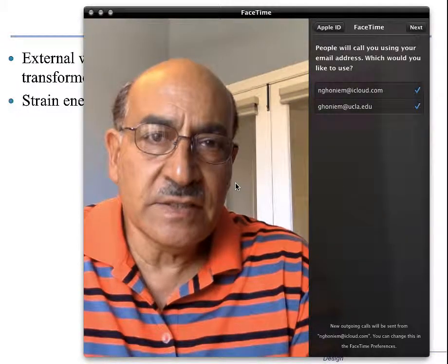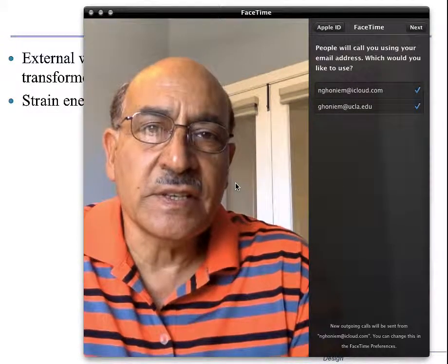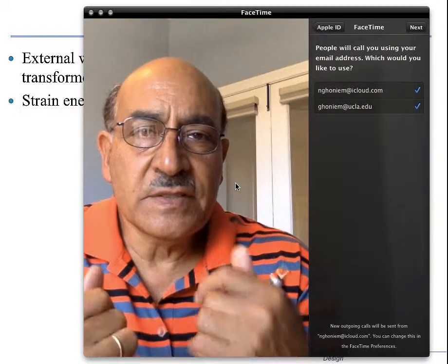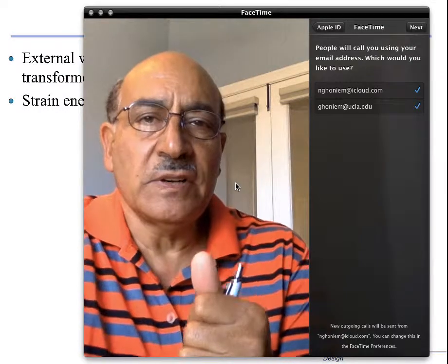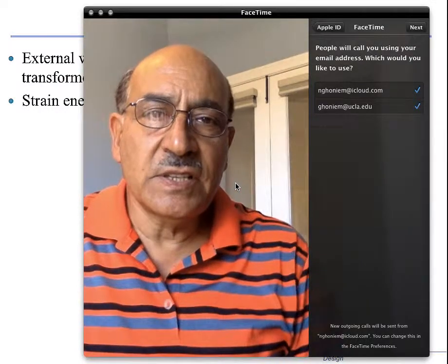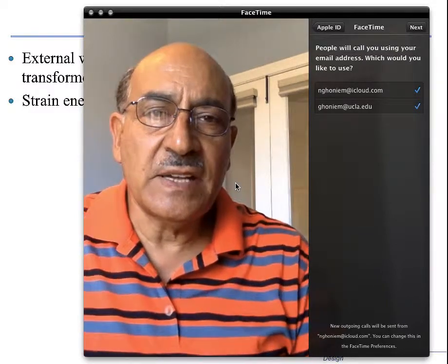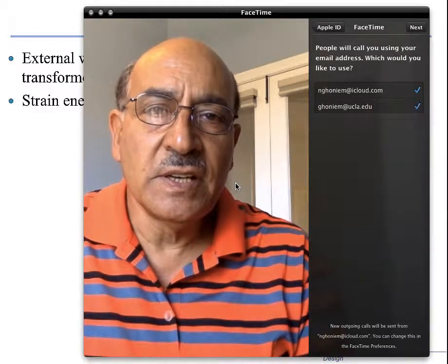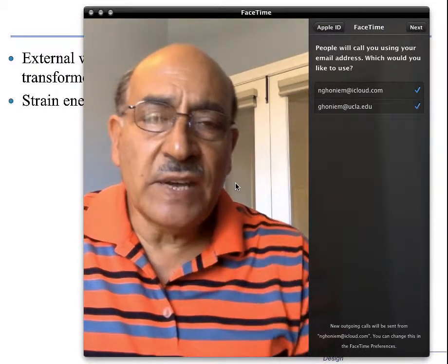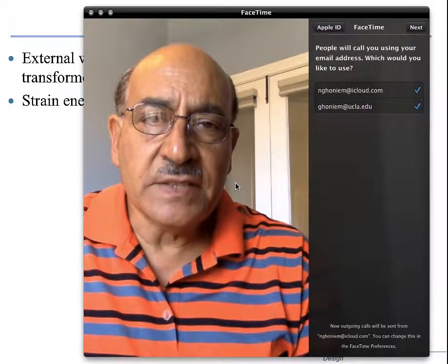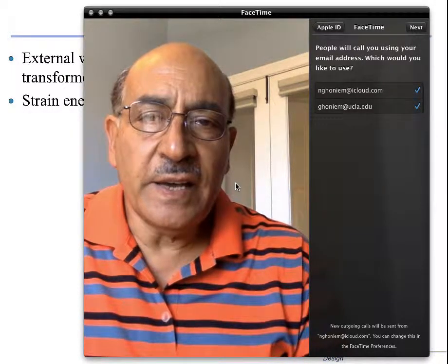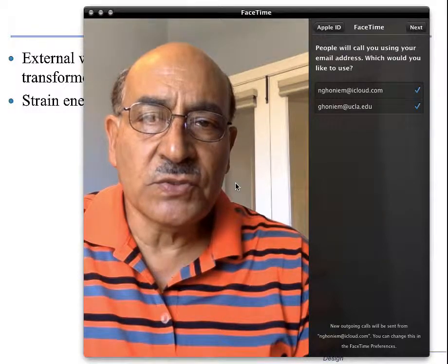So in fact, there's two elements of this presentation or this section. One element is number one, how to find the elastic energy stored in a section of a beam or a tension member or a torsion bar. And then number two, once you find that out, how do you utilize the expressions or the formulas that you'll get in determining deflections or rotations.